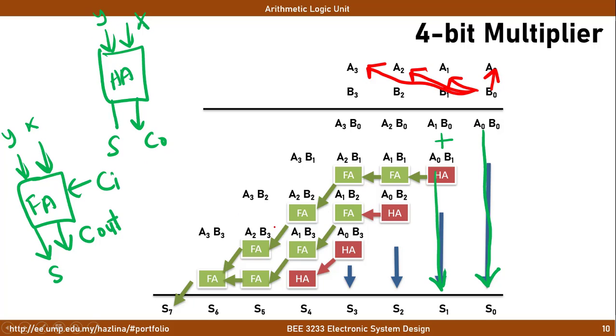and 2 output elements. So as being suggested here, the first tier of addition of the second stage can be done by using a half adder. For the second stage, you will require one set of full adder and also a set of half adder. Look at the fourth addition, in which it requires at least 2 sets of full adder to complete the addition, as well as a unit of half adder, as this involves 4 additions of numbers. Then 3 additions of numbers requires the same 2 full adders and also 1 half adder, followed by 2 half adders, and the final bit, which is equivalent to 1 full adder.